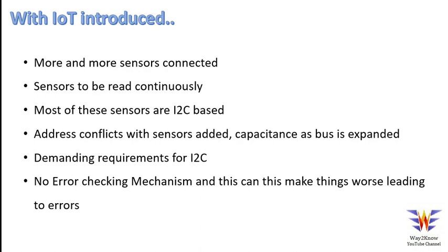So if you bring all these together, if you want a battery operated device, there is a power consumption that is happening. If you have a number of slave devices, there is no way you can check errors and then control the addresses. Address conflicts might happen. And if you want the slave to talk, you cannot do it without additional pins from the slave side, and definitely slave to slave communication is not at all there. So there are disadvantages with the current I2C.